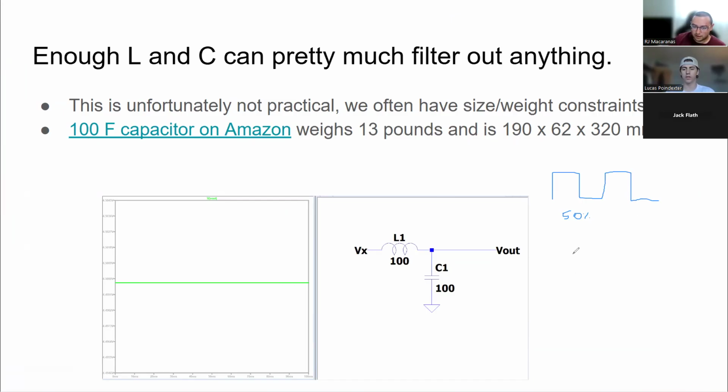And so as I put in 9 volts, and I'm switching from 9 volts to 0 volts, the DC value of this is going to be 9 volts times that 50%. And so you can actually look at the transfer function of the buck converter, which is what I was modeling in this case. The output voltage is related to, sorry, this is terrible writing, the input voltage times the duty cycle effectively.